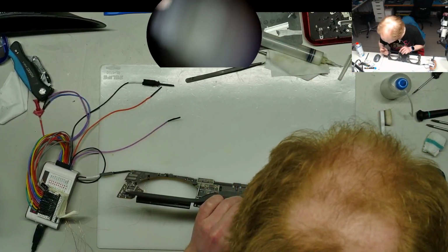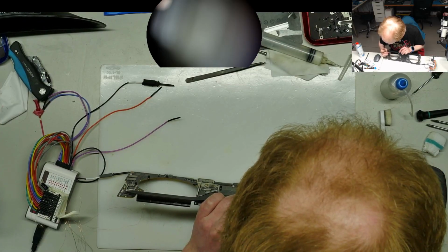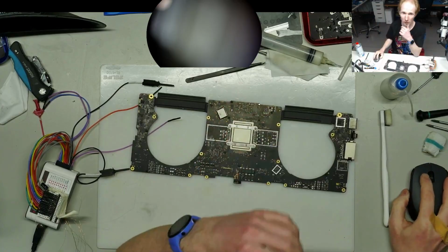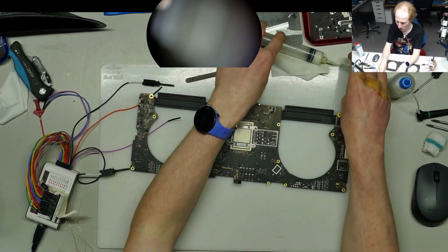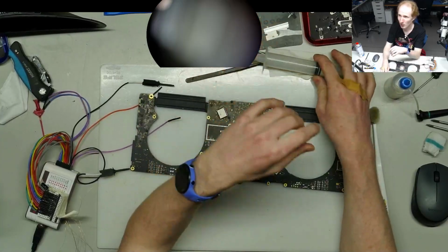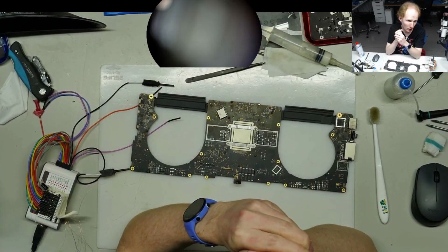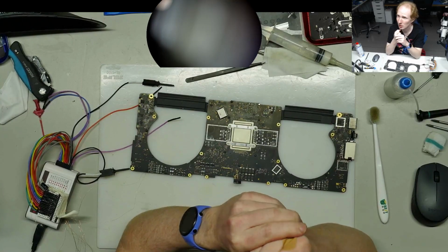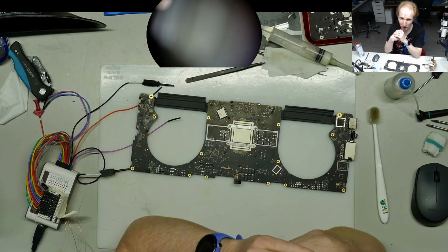So what we're going to do now is set it up to listen to the traffic of the board when we start it, because on init there will be a ping to all the amps. So we are going to find which amp is not responding to the ping, if any, because maybe there's something wrong with the reset line.